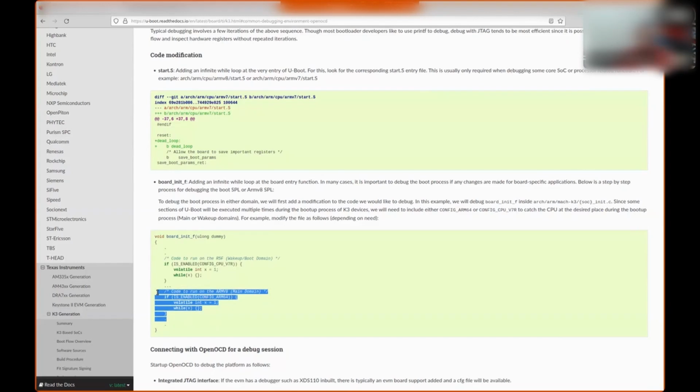Now, something to keep in mind, if you're working on AM64 or AM65, this is an exception case. TIFS, actually J721E, let me rephrase this. If you're working on J721E or AM65, in both these cases, TIFS is actually loaded by the R5 bootloader. So ROM will wait up to 3 minutes for TIFS to get loaded. And if it doesn't get loaded within the first 3 minutes, it will automatically trigger a watchdog for you. So you want to be careful about that.